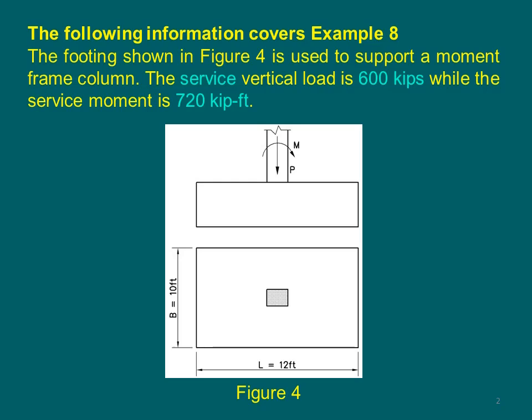The loads given here are service loads. It doesn't say if there's going to be dead load or live load. Therefore, I'm going to consider them to be dead load only. This is a very standard thing that we do if you don't really know if this is going to be dead load or live load. You just consider it to be dead load.